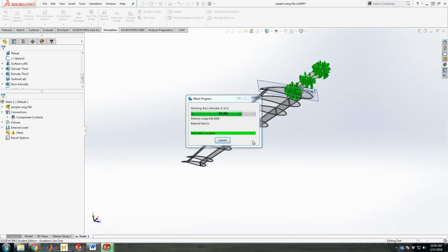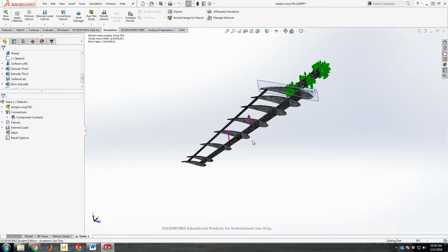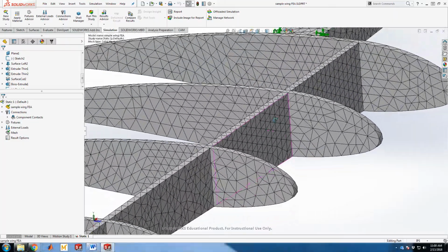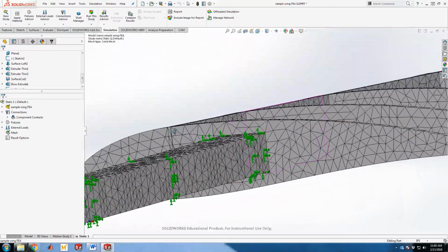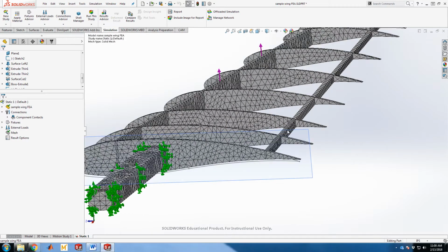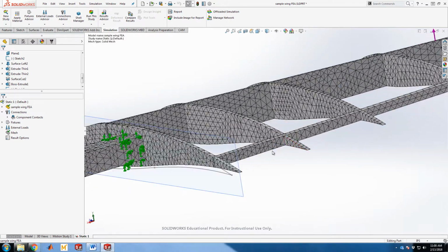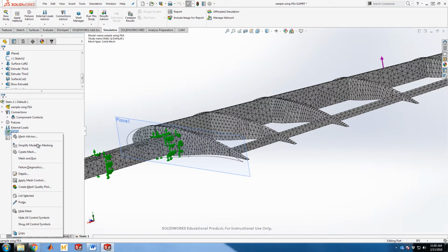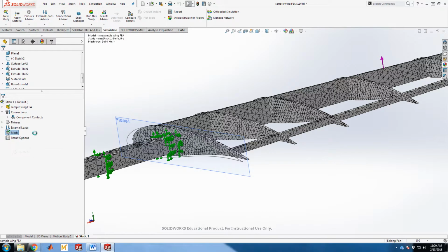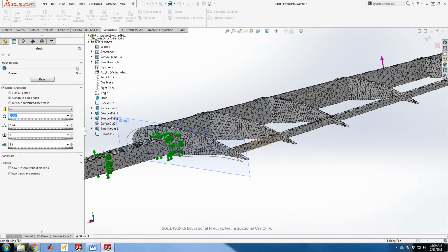Let's see here. Generates the mesh. Come on. Got it. All right. So this shows you kind of the level of mesh you're dealing with. It's still probably way too coarse for an excellent study. Just for kicks, let's do one that's way smaller. So instead of 0.2 max size, let's do 0.05. That might be on,